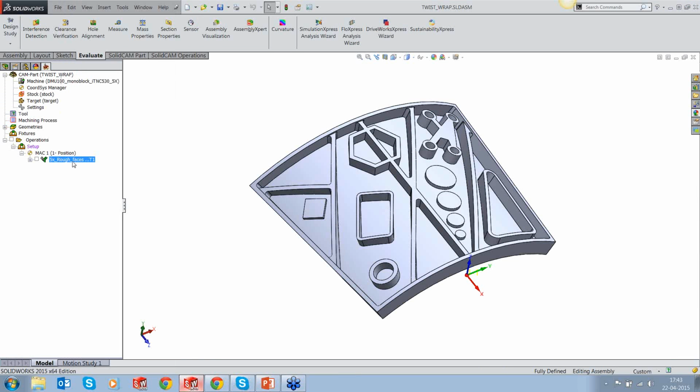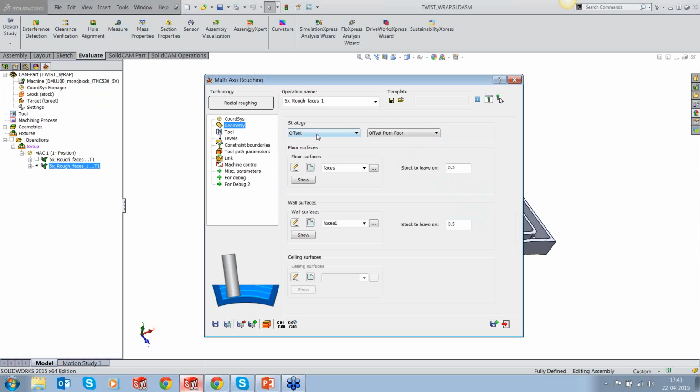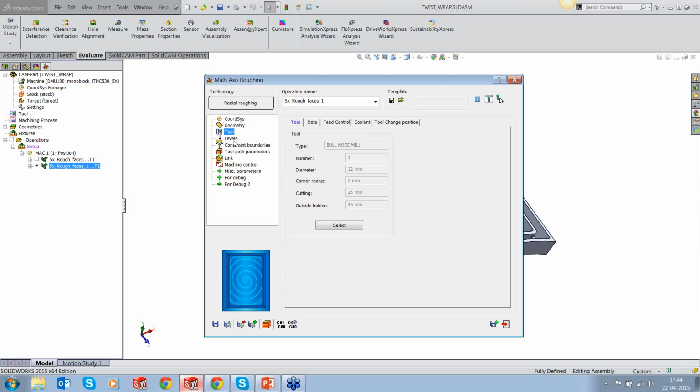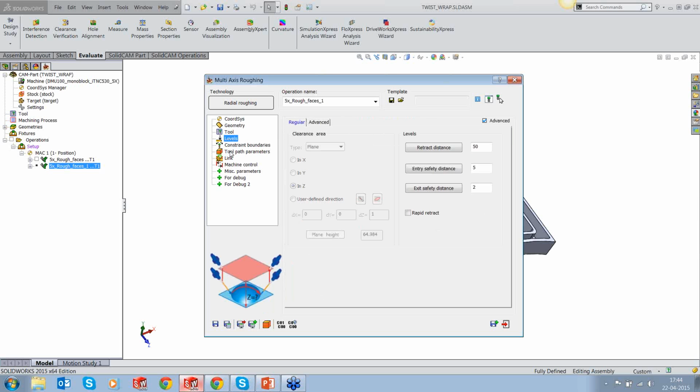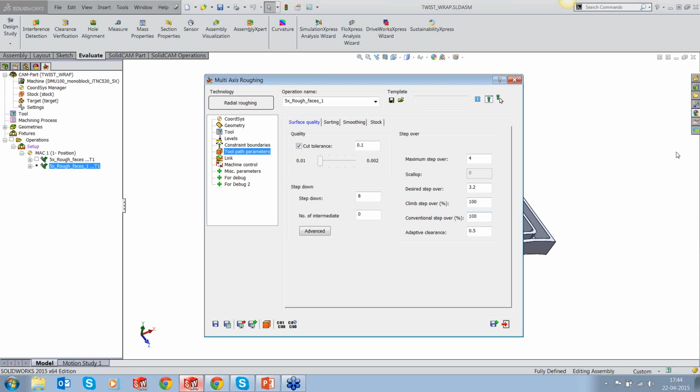What I'm going to do now is copy this example and toolpath and paste it, and we will change the type of machining or the strategy to adaptive to show you the adaptive strategy too, which is basically similar to what we have inside SolidCAM iMachining, where it tries to take constant load. The only thing is it will vary its side step, and the toolpath looks pretty similar to what we have in iMachining. So let's select the same tool, and the only change that we're going to make now is out here.